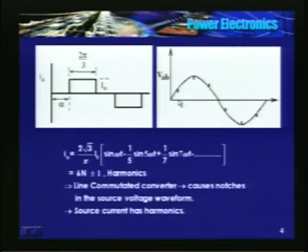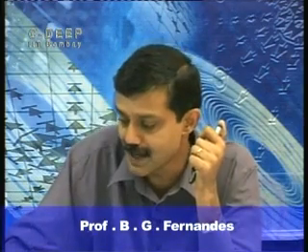The instantaneous value may become zero, and your control system says that is another zero crossing, and it takes some other action. So your control circuit may maloperate, as well as relays connected to the system may maloperate. These are the effects of harmonics.